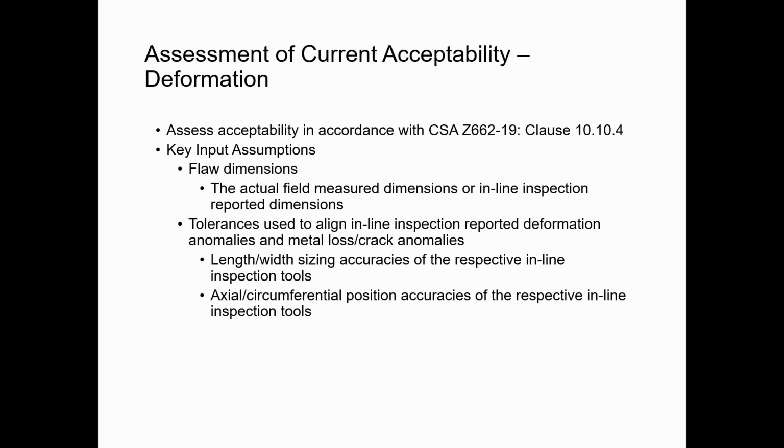And you consider tool tolerances once you've done some excavations, or, well, you must consider them when you do the remaining life calculations. But I think developing a compliance program for inline inspection incorporating the tool tolerances might be just a little conservative until you understand how well or how poorly the inline inspection tool sizing and accuracy performs.